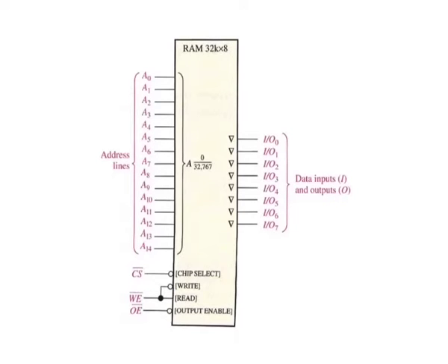Tri-state buffers in a memory allow the data lines to act as either input or output lines and connect the memory to the data bus in a computer. These buffers have 3 output states: high, low and high Z, that is open. Tri-state outputs are indicated on logic symbols by a small inverted triangle and are used for compatibility with bus structures such as those found in microprocessor based systems.